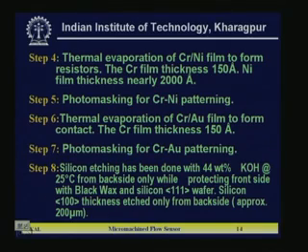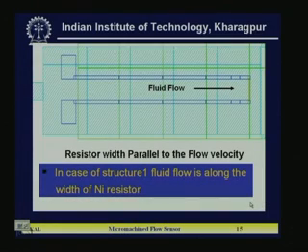So, that is normally done, otherwise you have to go for some other etching technique, micromachining technique, not KOH, those are basically TMAH etching. TMAH etching is not available in most of the laboratories, that is why using KOH also people design the process flow, so that easily you can get the complete structure. Okay.